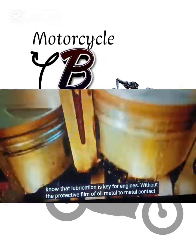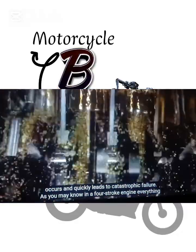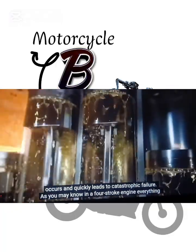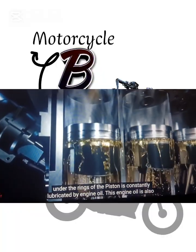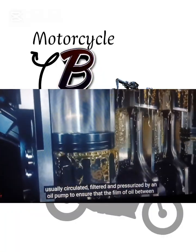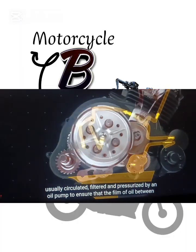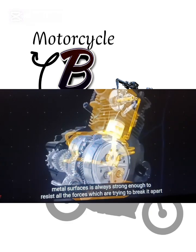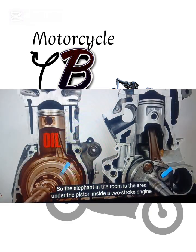is key for engines. Without the protective film of oil, metal-to-metal contact occurs and quickly leads to catastrophic failure. As you may know, in a four-stroke engine, everything under the rings of the piston is constantly lubricated by engine oil. This engine oil is also usually circulated, filtered, and pressurized by an oil pump to ensure that the film of oil between metal surfaces is always strong enough to resist all the forces which are trying to break it apart. So the elephant in the room is the area under the piston inside a two-stroke engine.